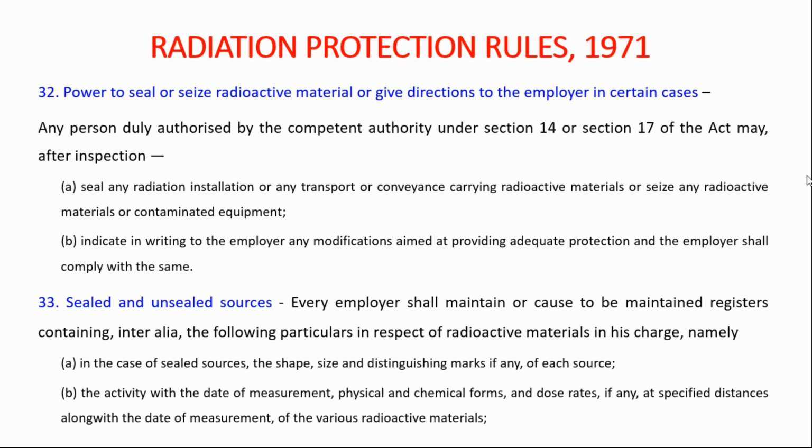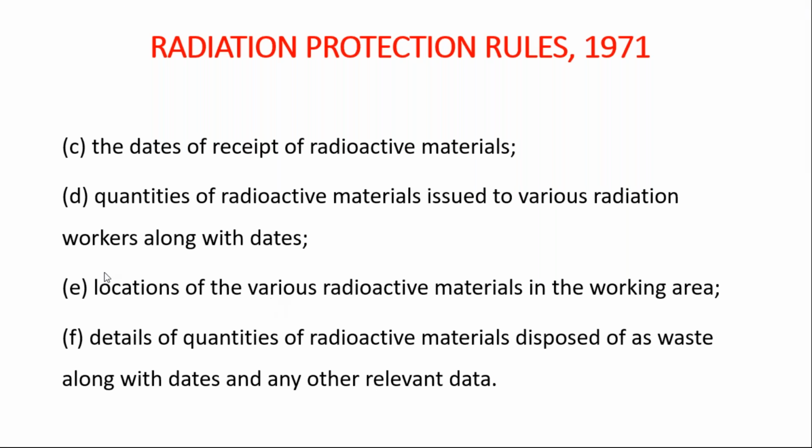The dates of receipts of radioactive materials should be recorded and preserved. The quantities of radioactive materials issued to various radiation workers along with the dates. So whatever material is going to be handled by the radiation worker should be recorded with quantities and dates. Location of the various radioactive materials in the working area. We have to record these locations, these installations, these equipments, these departments where these radioactive materials are going to be handled by the radiation workers. Details of the quantities of radioactive materials disposed of as waste.